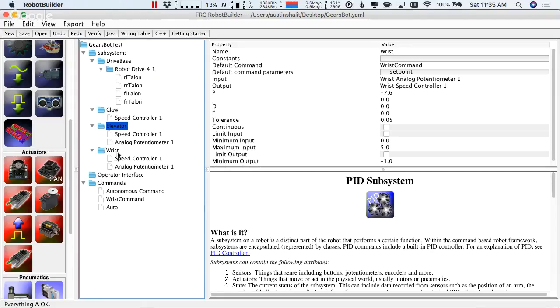And what that means is for some sensor error, we're giving the motor some output. So when we're 10 centimeters away, we're giving it full power. And when we're 5 centimeters away, we're giving it half power. And when we're right on target, we're giving it nothing. You could say that the speed of the motor is proportional to the error, which is why it's called proportional control. And then integral: